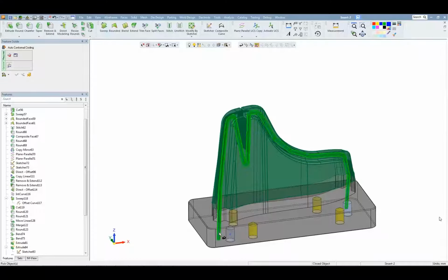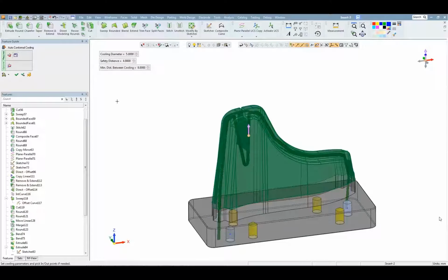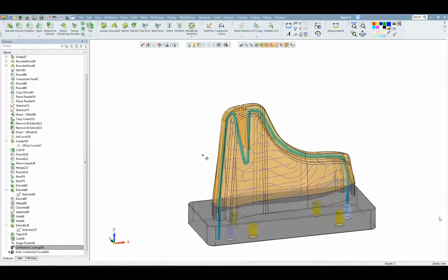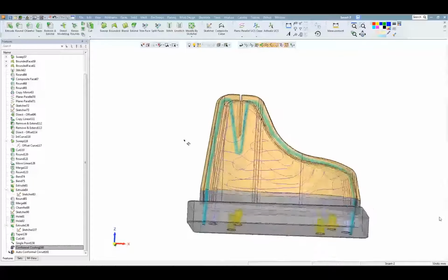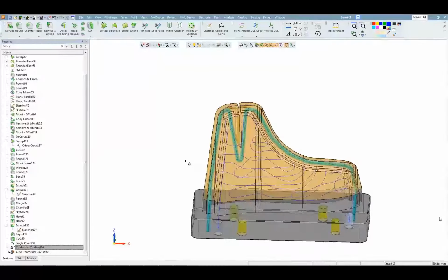We can set our existing cooling channels, so we can say we want to enter these existing cooling channels. We can set our in and out positions, our entrance and exit positions. And we can auto-generate a spline curve which maximizes the use of the tool as such. So this is getting to a very good point of use of this insert as such.